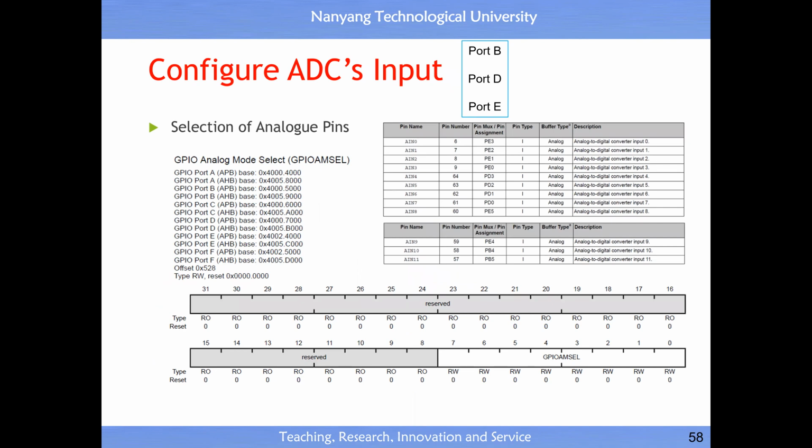First, you must tell the hardware, because you can have 12 sensors. If you connect one sensor to one of these pins, once you do the connection, let's say you choose a pin of port E, then here you must find port E, which has a list address. Then in this address, what is the corresponding pin of port E? Let's say pin 2 of port E. Attach your sensor, then to control pin 2 you must set this bit to be 1. This just tells the hardware where the sensor is connected.